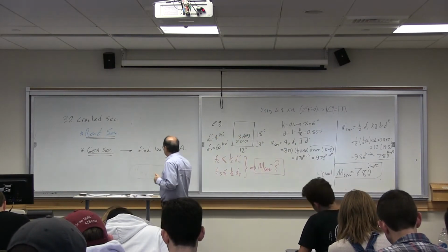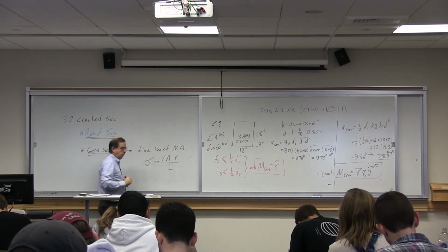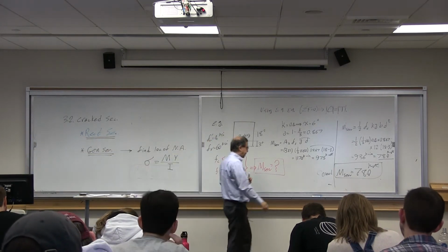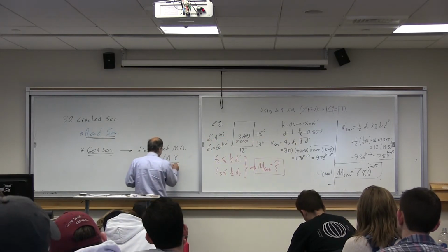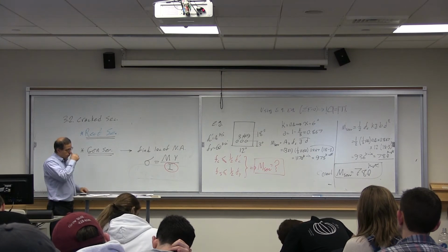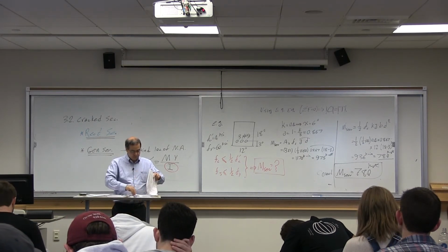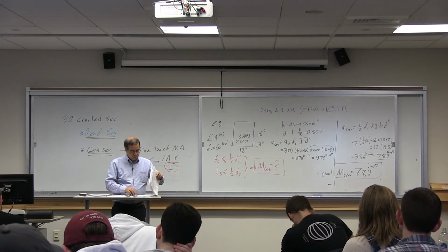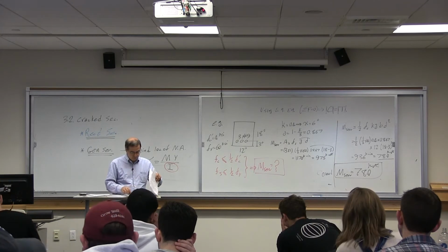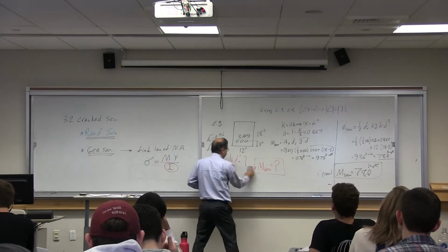Then you would relate stress to moment through My over I. In order to do this, I should be calculated for the cracked section with respect to its neutral axis. So let's calculate the moment of inertia of that section.